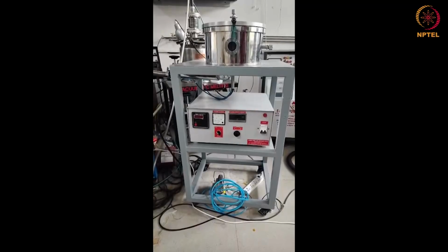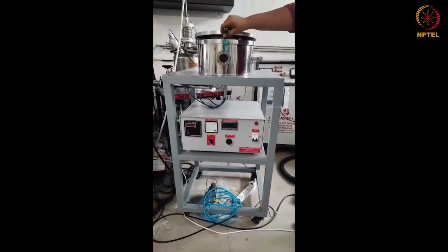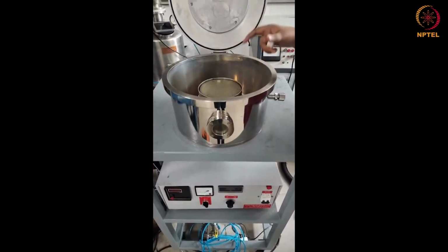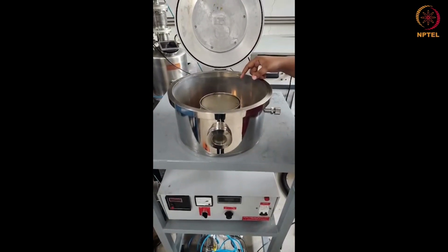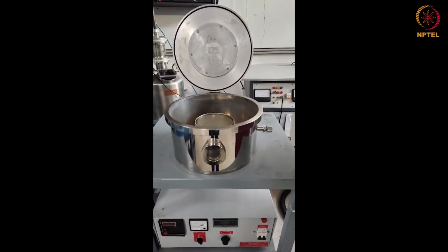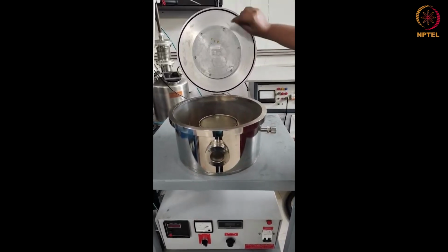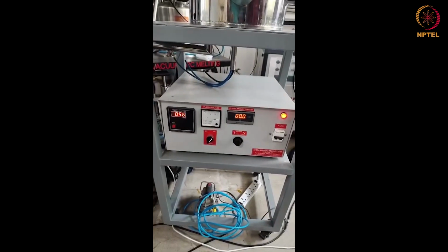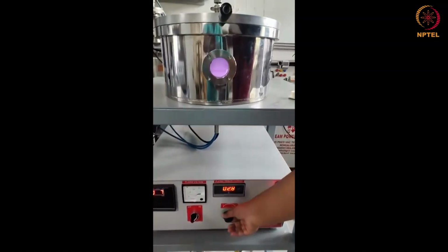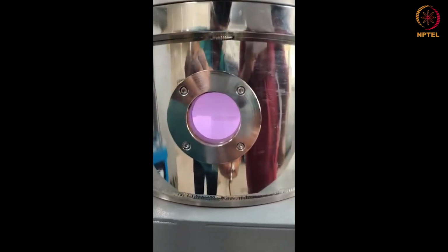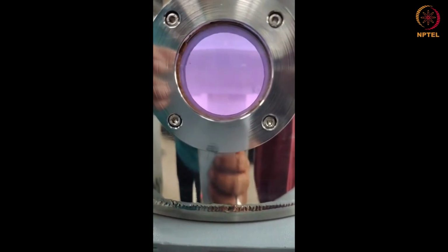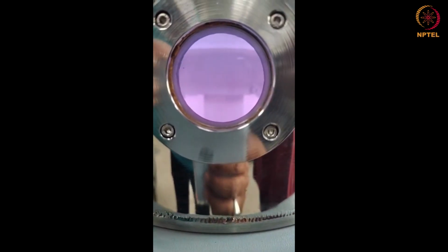This is a plasma treatment setup. Here it has a vacuum chamber with a plasma gun, where a high frequency voltage in the order of megahertz to gigahertz is applied, which ionizes the gas present inside it. Here we place our substrate. After achieving a vacuum, we supply voltage and plasma is generated. These ionized particles bombard the substrate and cause physical and chemical modification. It can be used for surface cleaning and surface processing.